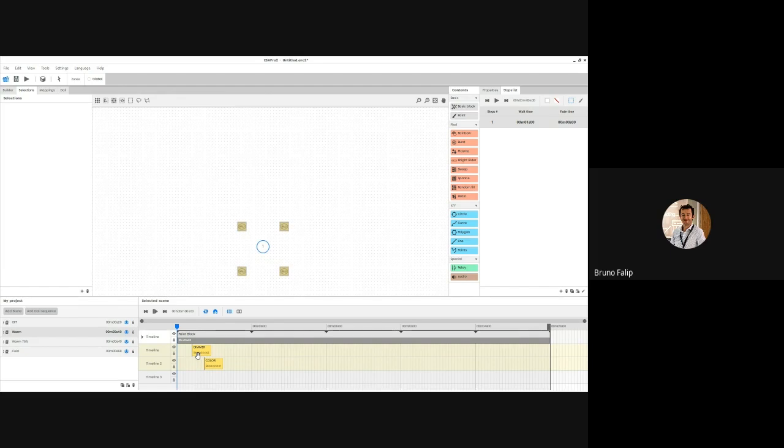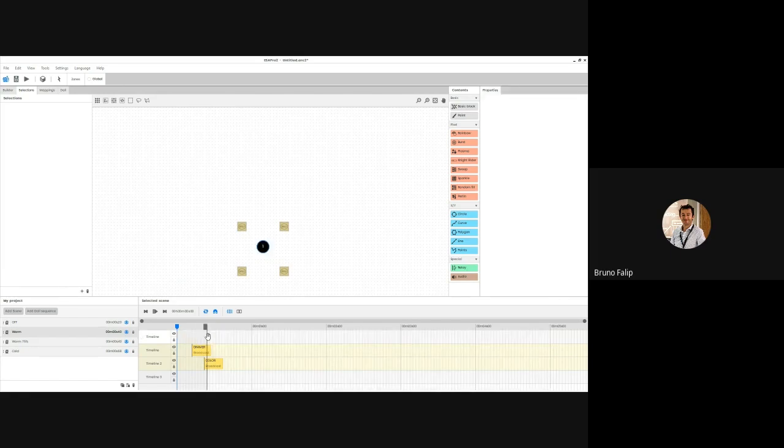I mean, I've done that this morning by mistake when I was programming our building, and I discovered that I had a scene running, and it was sending some commands to the bus, and it was going crazy. So make sure you unselect the loop option. So let's remove this. I don't need it now. So when you're done with this, you can write the memory of your controller.